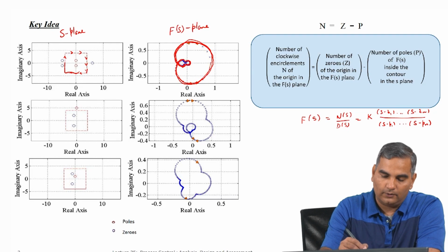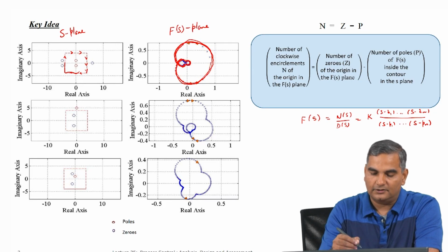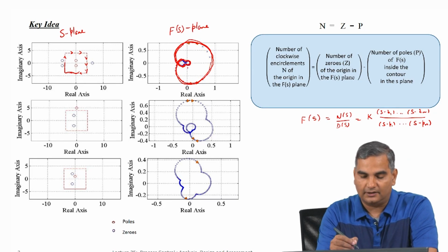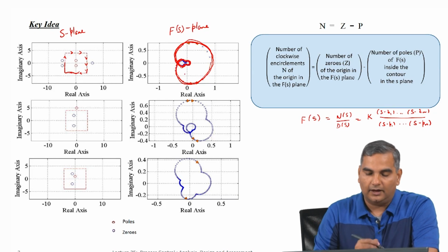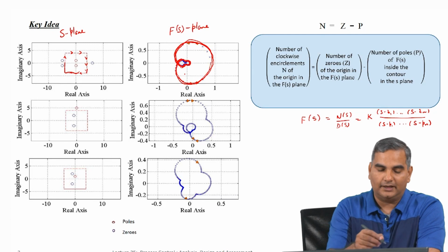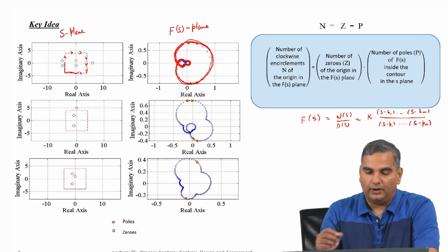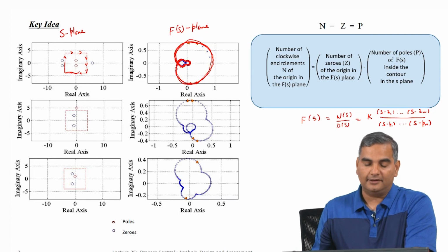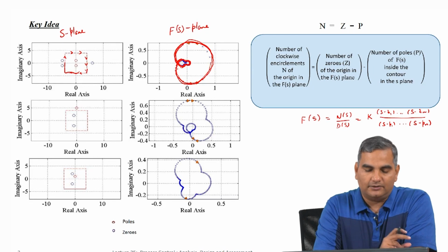Now, I go around and come back here. Now, forget the outer circle, from here to here I continue to circle and the origin is inside. You will see I have made another circle again in the anti-clockwise direction around the origin. So, basically when I convert this contour, which is the clockwise contour in the s plane, to an f(s) plane, in this case I seem to have made two counterclockwise encirclements of the origin.